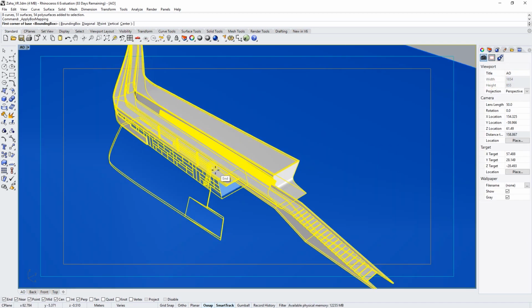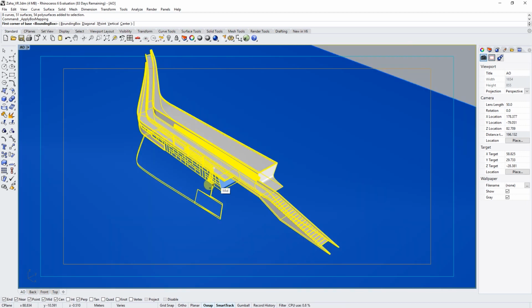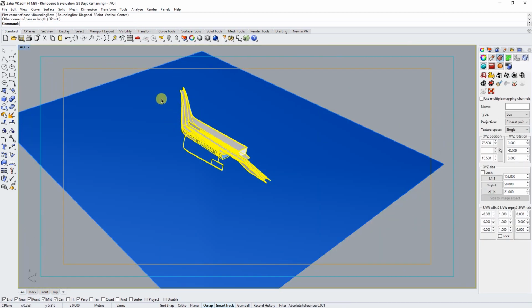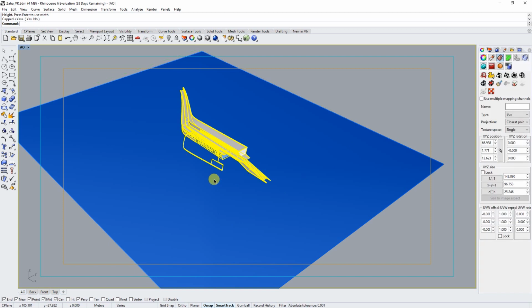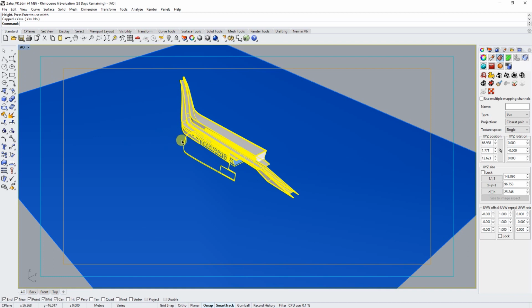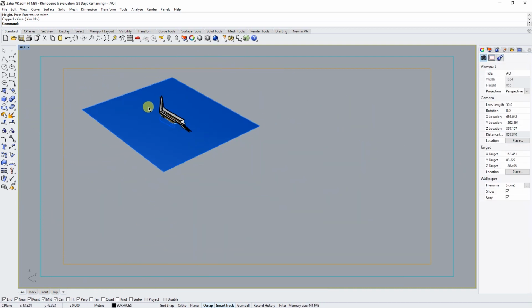Which is here. So if you're not using a material, if you're using a tiled material, you need to apply just a global box mapping. That wasn't a great example. Just a really rough one, and just cover it all and use the global coordinates up in the top left. Just go yes, yes, yes. It's fine if you're using like a homogeneous texture or whatever, but if it's a tiled one, your bricks will be one way on one surface and another way on another surface. So the way to get rid of that is just with the global box mapping.